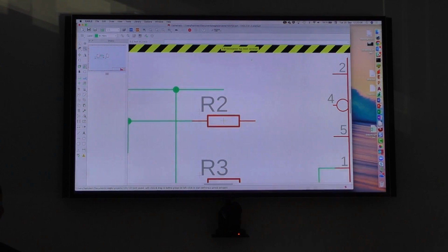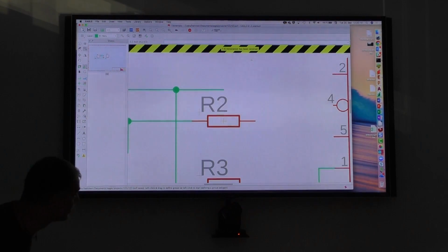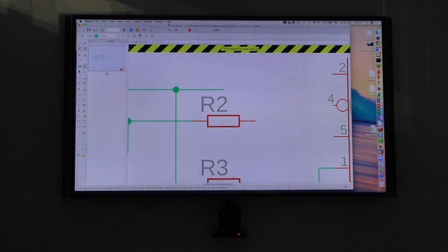Is there a mechanism? For example, if you add another resistor here now, and then save that, and then open up the board file, it will say not consistent. How can I then add that resistor? There's no convenient way. You have to place it manually, name it identically, choose the value, and do the connections. So you have to do this manually.